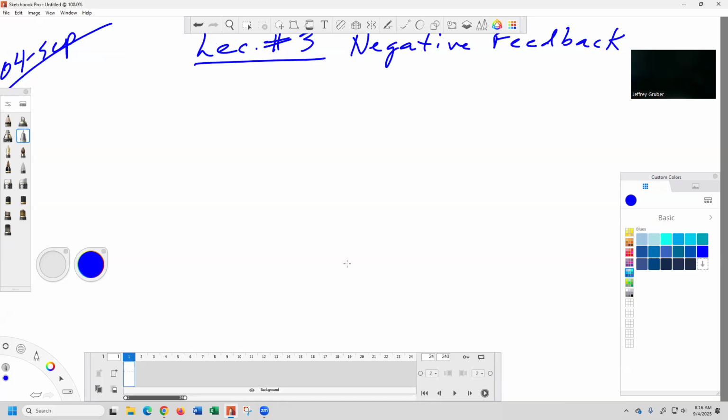So I just want to go over negative feedback. I just kind of hand wave. I drew those three topologies, which was an inverting amplifier, a non-inverting amplifier, and a voltage follower. I just drew them, and they all have negative feedback. They have a feedback loop. So open loop means there's no feedback. So what happens if an op amp is open loop?